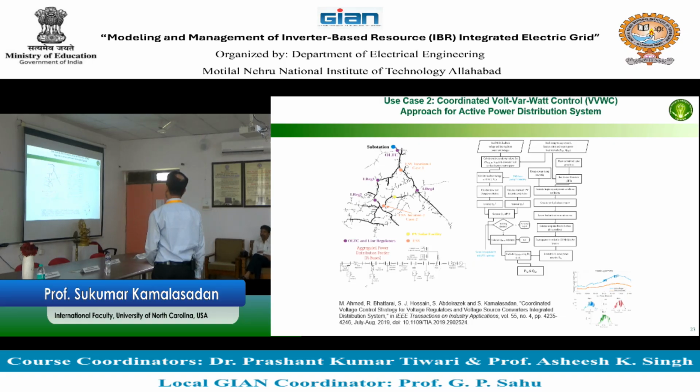We talk a little bit about the extension to volt-watt. So this is actually a feeder, also a real-life feeder. This feeder is in North Carolina. It has 8,500 nodes. This is the OLTC, and these are regulators, 3 of them, and these are our laterals. We are looking at 2 energy storage locations, and these locations are used for volt-var control.